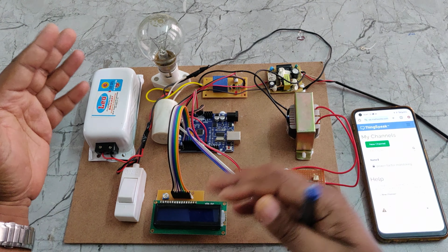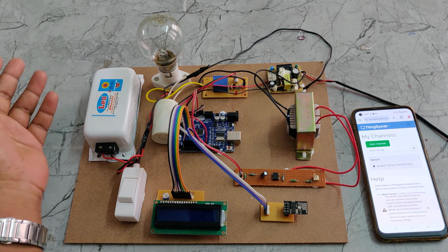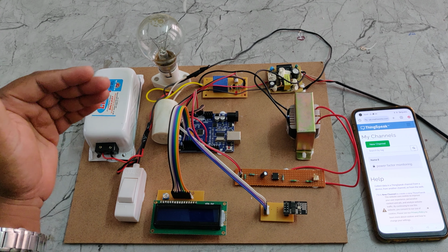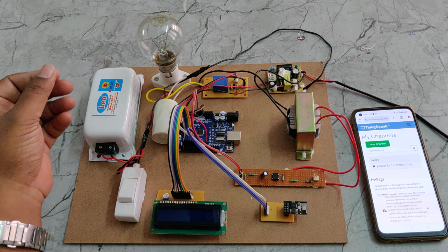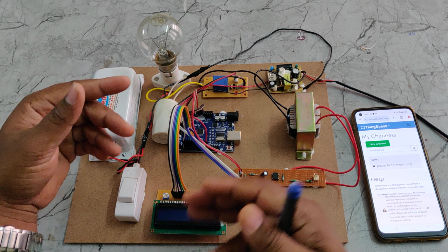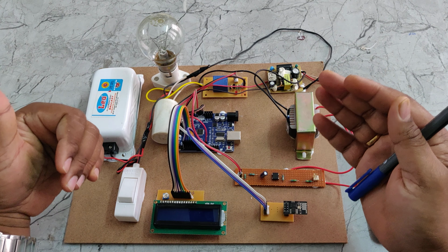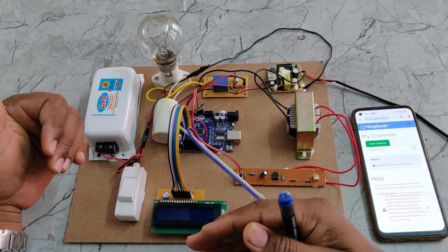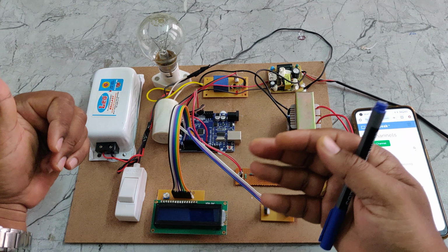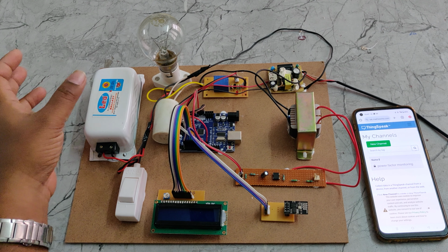For example, if we connect a resistive load, then the phase difference between the current waveform and voltage waveform is nearly 0. Then cos 0 is going to be unity, which is 1. And whenever the phase difference increases, the theta value increases, so the cos theta value comes down from 1 to around 0.9, 0.8, like that. Based on the phase difference value, we get the power factor value.